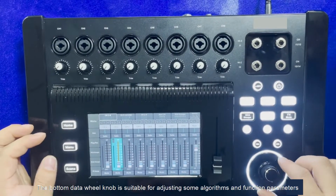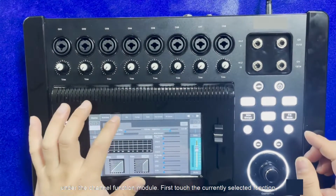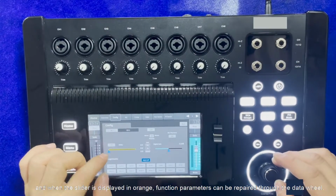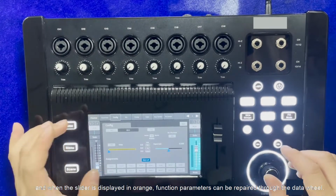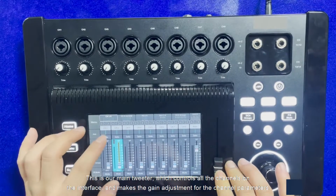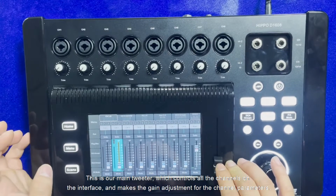The bottom data wheel will now be suitable for adjusting some algorithms and function parameters under the channel function module. First touch the currently selected function, and when the slider is displayed in orange, function parameters can be adjusted through the data wheel. This is our main pusher, which controls all the channels on the interface, and makes the gain adjustment for the channel parameters.